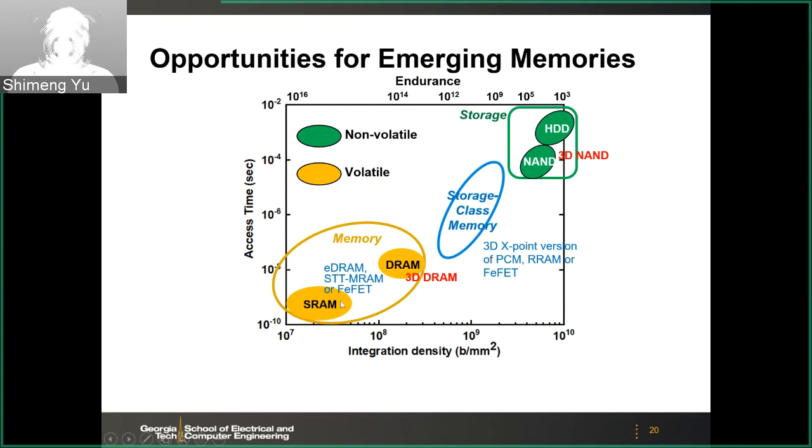And also for the gap between the SRAM and DRAM, the idea is to introduce some last level cache made of some emerging technologies. Of course, IBM has the eDRAM, embedded DRAM, but we see opportunities for other emerging technologies like the STT-MRAM, the magnetic random access memory, and also the ferroelectric devices. So they may play a role in the future system. But of course, those new technologies are still under research and development. But the industry is investing a lot in those new technologies these days.